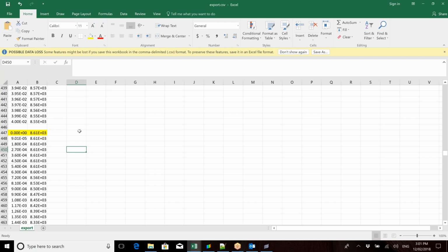In terms of the amount of displacement that it's showing, it isn't necessarily correct. So you need to then start to run your optimization on it, put in your engineering judgments to find out how to properly design your crash structure. But this is the big part here that you want to be looking at, is your kinetic energy to internal energy transfer. So I'm not too sure whether it is exactly 350 kilos at 7 meters per second, but if that's the analysis set by the FSA rules, and you've set the model up 100% correctly as to what it would be on your car, or however they want you to set it up for their test. So again, if they have a certain way of you setting it up for your test, set it up for that.